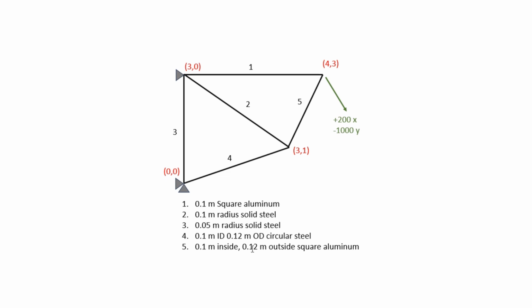And so what we are going to learn how to do in this tutorial is first generate line elements and then turn those elements into beams and assign cross sections and material properties to each one of those beams.